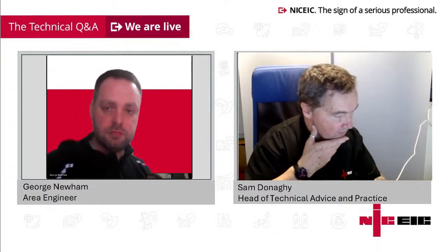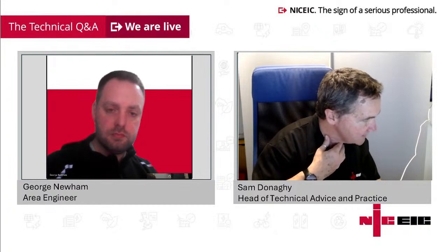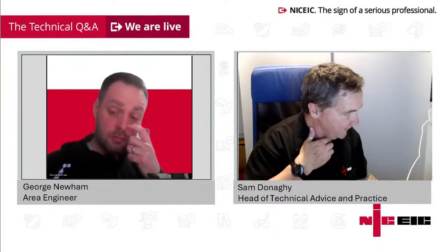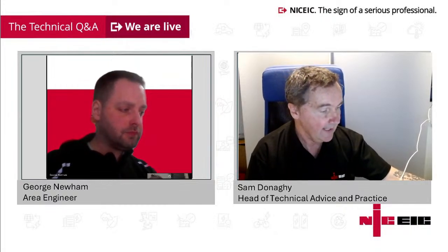The other thing is, with 1361, if I remember rightly, and I'm just going to check this while we're talking, yes, if you go to page 386 of 7671, which is part of Appendix 1, and Appendix 1 covers all of the British standards that are referenced within 7671, and on page 386, if you look at BS 1361, it says it's been replaced by BS 88-3, so you can use the BS 88-3 time curve to give you that information, because 1361 is a very common supply cutout fuse standard.